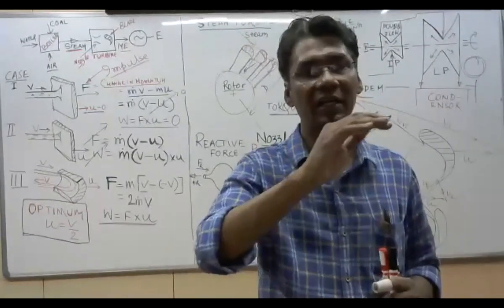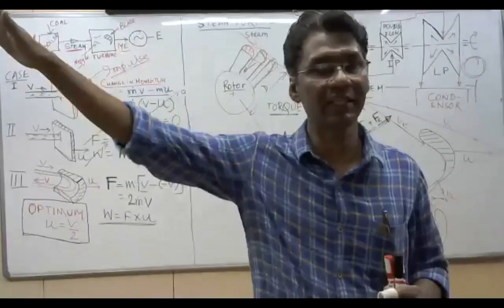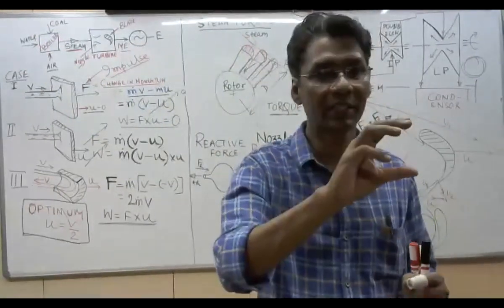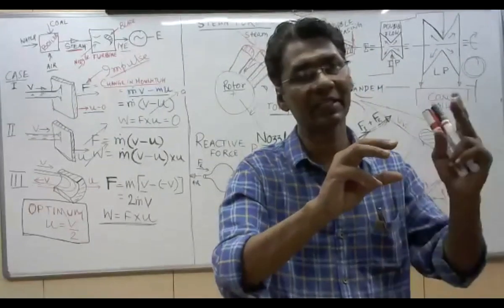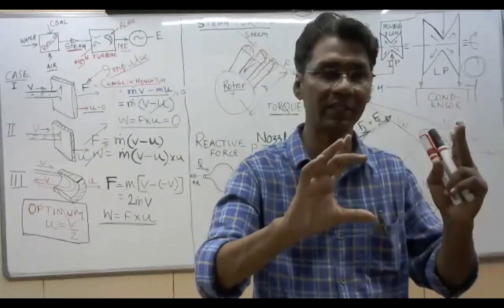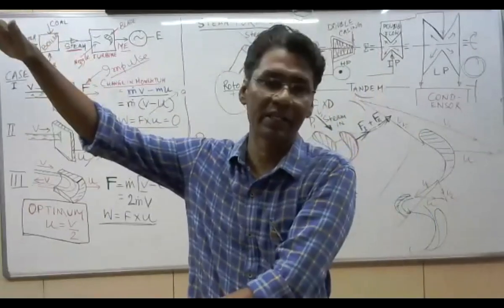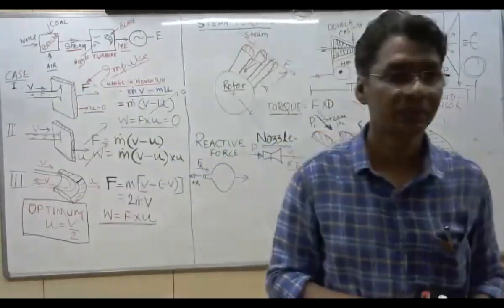Because the pressure in different stages of the turbine is different, the blade size is different. If the volume of the steam is less, that means pressure is high, and we have smaller size steam blades. If the volume is higher and pressure is low, in that case we have bigger size steam blades.